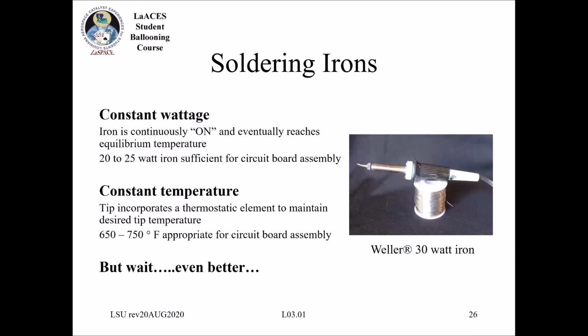So, soldering irons, and we're going to show you more details of this because this is what you are going to be using. It's constant wattage, so the iron is continuously on and eventually reaches an equilibrium temperature. That means when you first turn it on, it takes a few seconds to heat up to whatever setting you have. And then there's a tip on it that incorporates a thermostatic element to maintain the desired temperature.